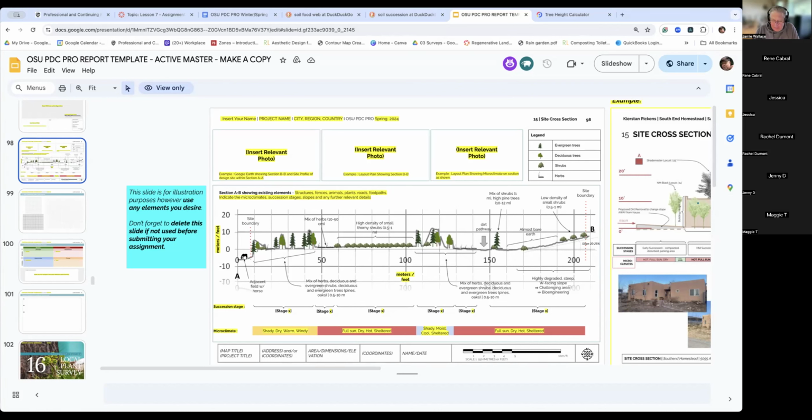And just so you know, typically stairs are 6 to 8 inches in height, and you can figure it out that way. I'd highly recommend you always keep your stairs the same height. For some reason, our brains get accustomed to the same height of stair tread. So if you put in a 6 inch, an 8 inch, a 10 inch, you'd be confusing many people that were using it. So yeah, try and keep that all consistent.